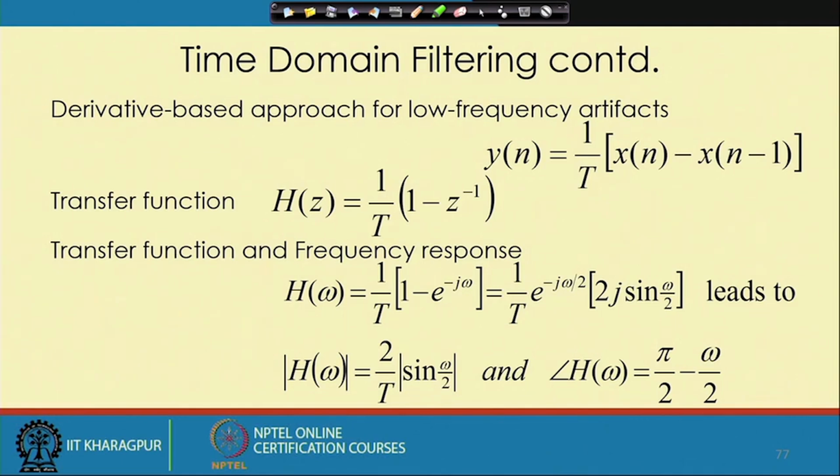So far the filters we have seen, that is moving average filter and synchronous averaging, are primarily used, or good, for removing the high frequency noise. Now, when we are going for the low frequency noise, that is baseline wandering, then we need to go for a little different kind of filter, and we need to go for a derivative filter.